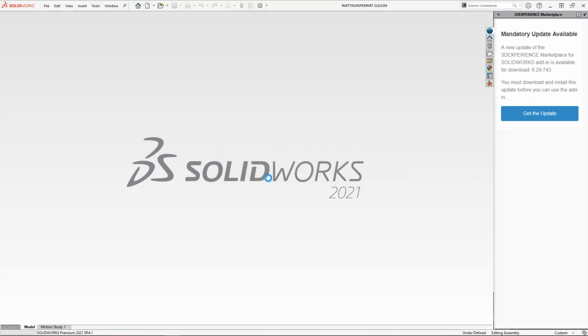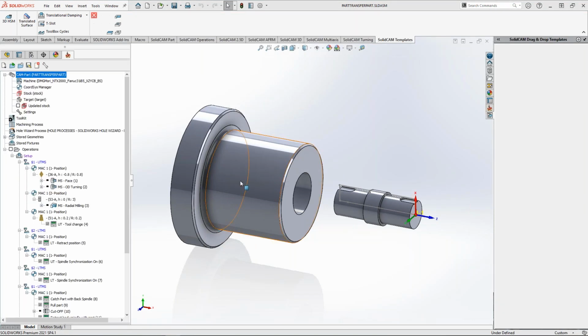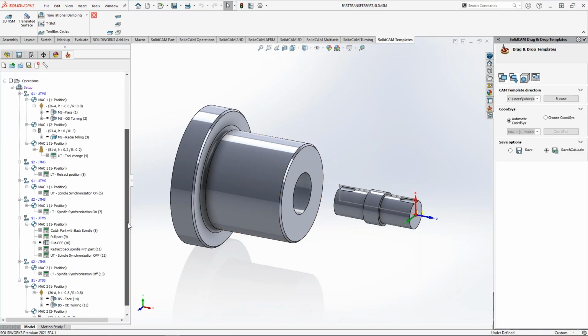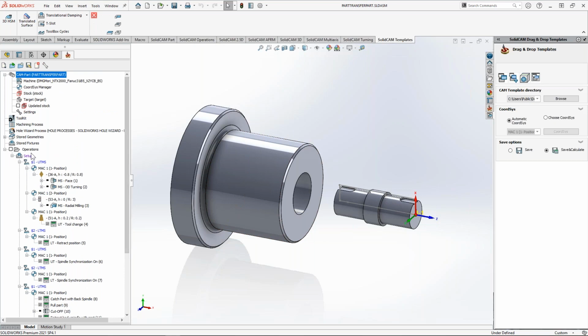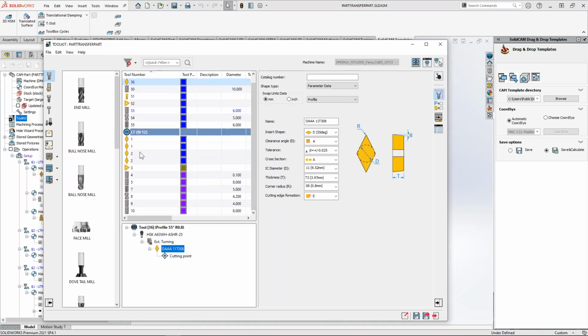You note that I did everything in 2019. The reason why I did that is that now, as you can see, there are no missing tools. Everything is fine. Before I recalculate, I can go to the toolkit, and you can note it is now a bit different. Now my lower turret is also assigned, but I don't have any kind of storage.